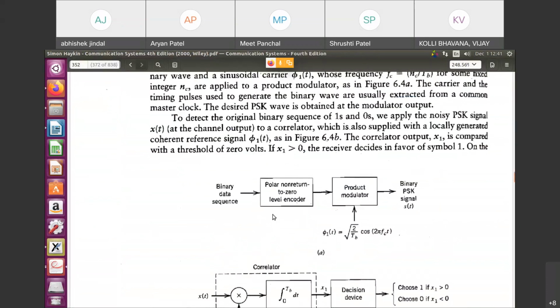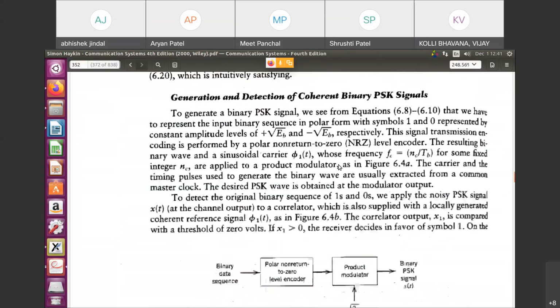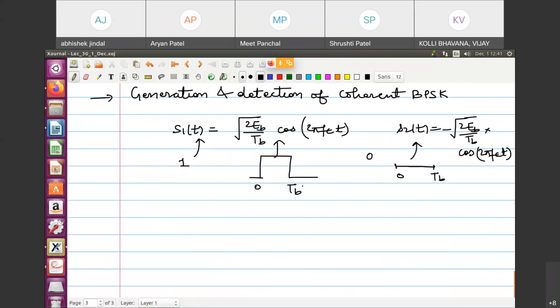So one thing we can do is that we can represent 0 by minus 1 as well. For the case of BPSK, we can smoothen it out. One way to do it is that if I say that 0 is represented by a level of minus 1, because that way I can simply multiply my NRZ waveform with the carrier level.